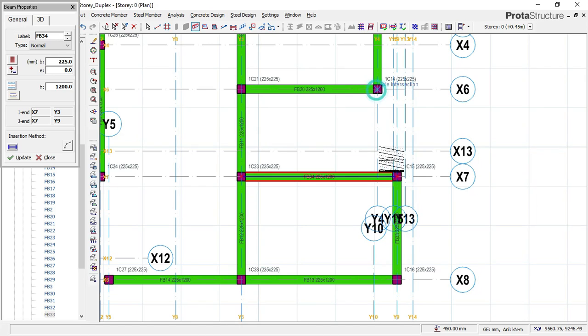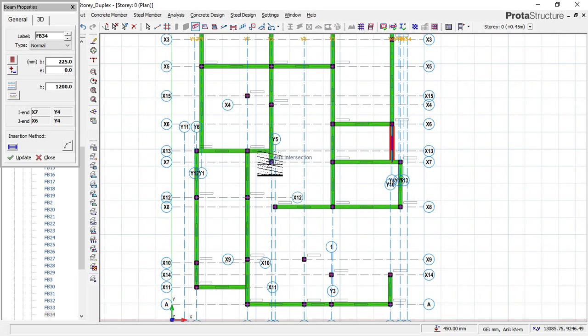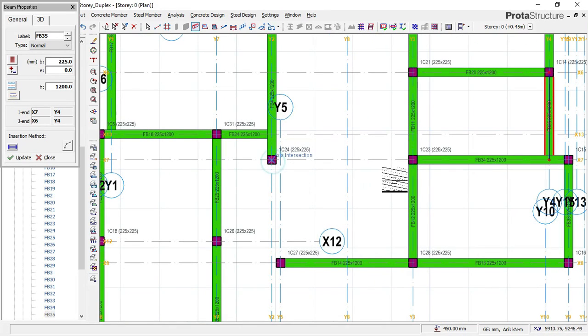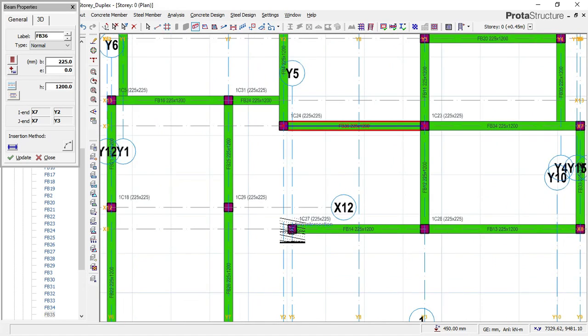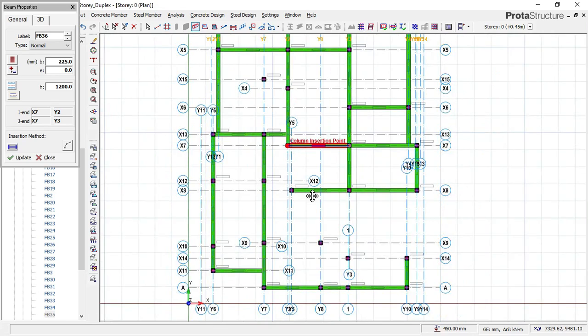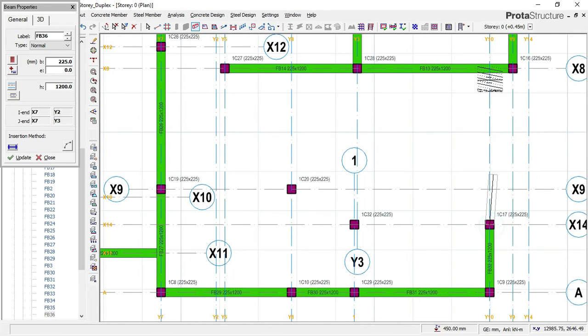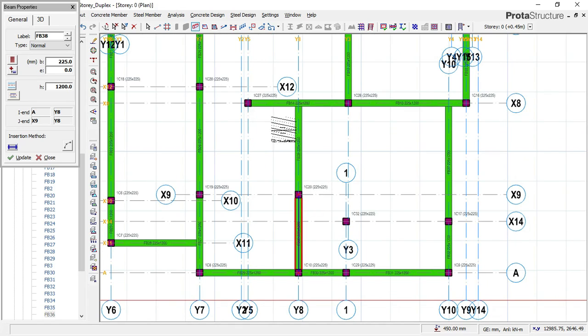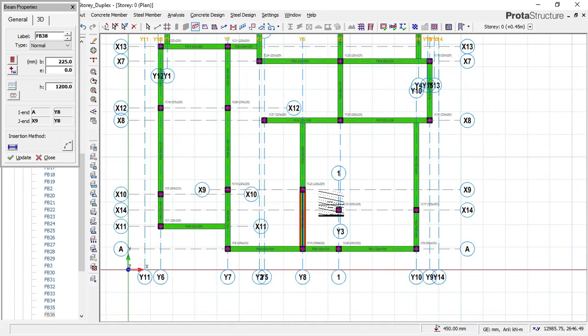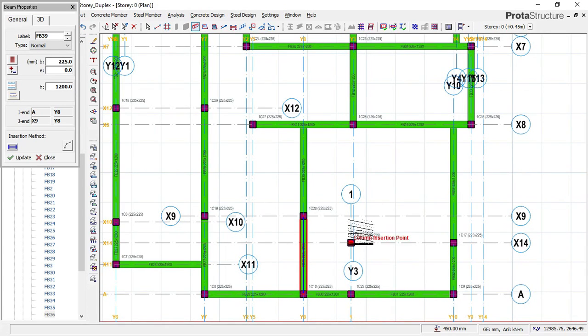Else, I'll say that you should go and use a pad foundation. And another type of foundation that you can use before you resort to a raft foundation is a wide strip foundation, where you have a footing and also a ground beam. Okay, let me just finish up here, and if you're having any confusion on how to insert your ground beam, you can go back to your first floor, story 1, to check how your beams are arranged on that area.